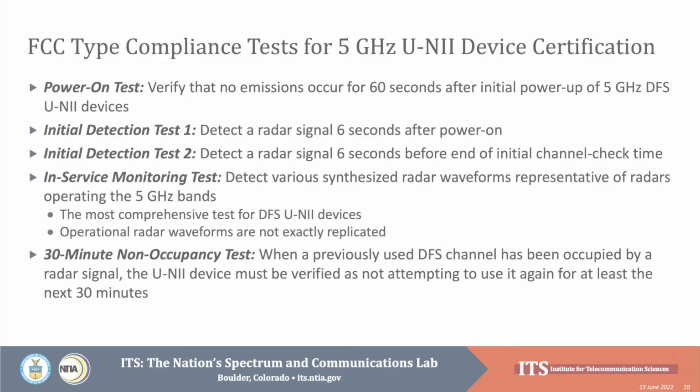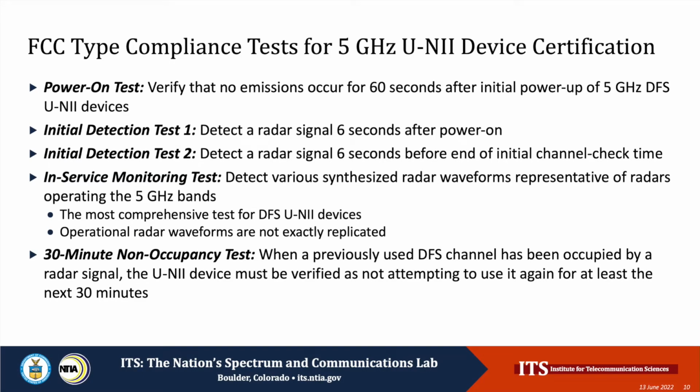Here's the flavor of what had to be done in this testing. First, there had to be verification on power on of a DFS system that no DFS emissions would occur for 60 seconds after initial power up. This system has to remain quiet after the on button is pushed for at least 1 minute. Any radar signals present when power on occurs had to be detected within 6 seconds. And radar signals have to be detected 6 seconds before the end of any initial channel check time by a DFS device.